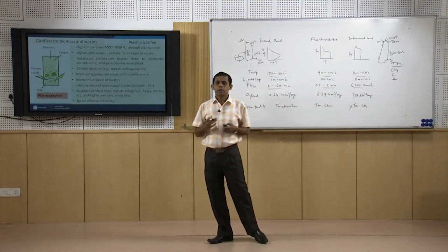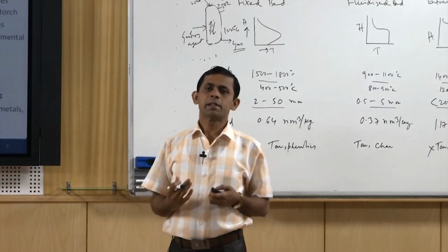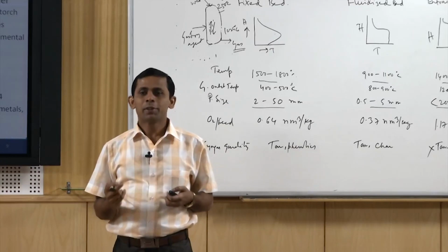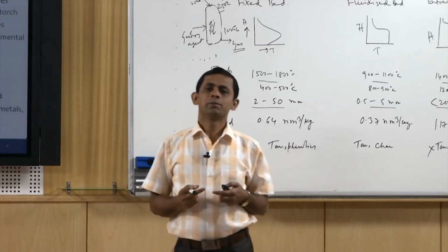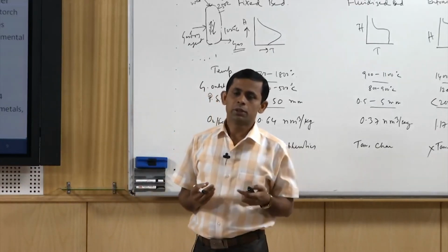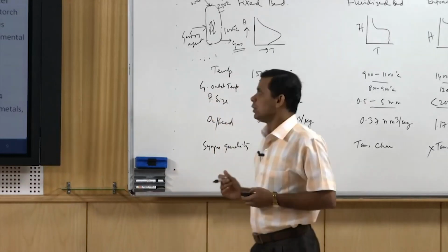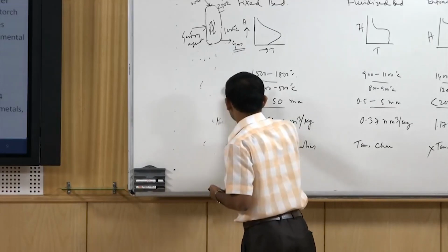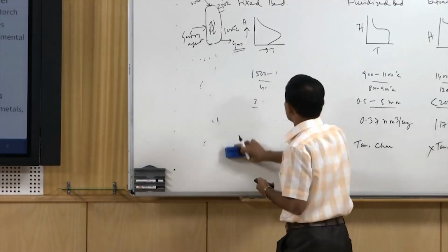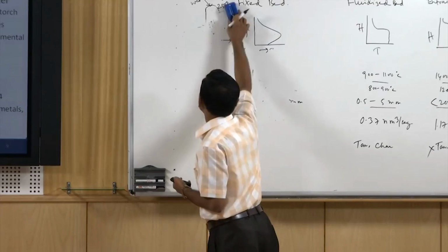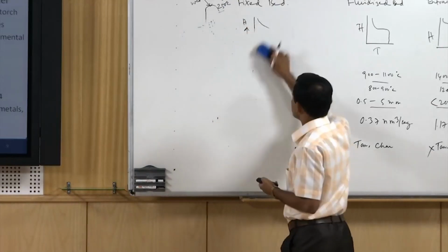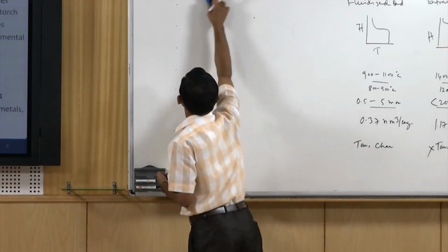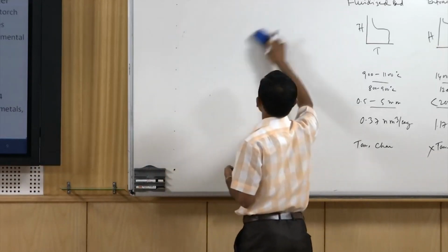Later on, a new type of gasifier has been developed for the gasification of biomass and waste, particularly those portions of the solid waste that are hazardous in nature. This new type of gasifier is called the plasma gasifier. In the plasma gasifier, unlike other conventional gasifiers, we do not need to send gasifying agents like oxygen or steam.